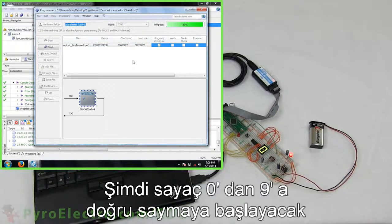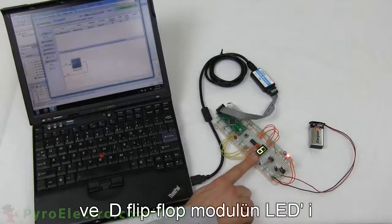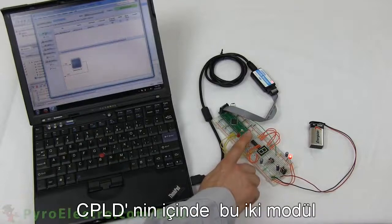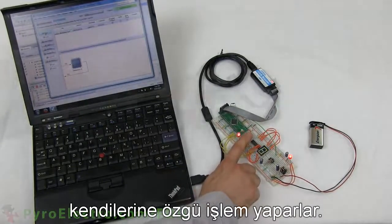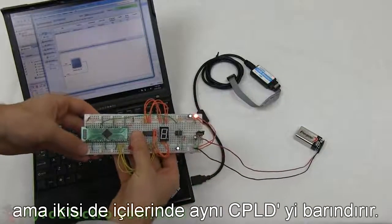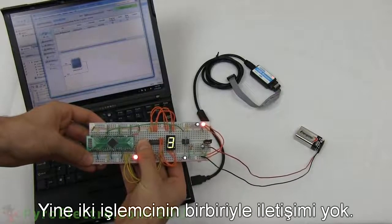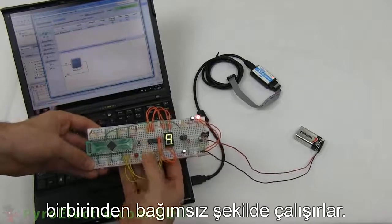Right away, the counter starts counting from 0 to 9, and the D flip-flop module turns on the output LED when I press the button. Inside of the CPLD, these two modules are separate and operate in two unique processes to achieve different goals, but they exist inside of the same CPLD. Let's get a closer look at the board. Again, the two processes don't know about each other, so they operate seamlessly and independently.